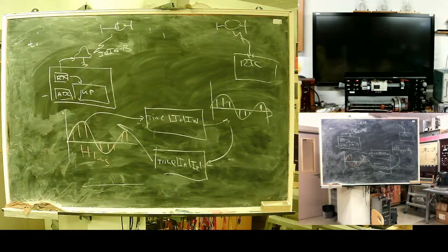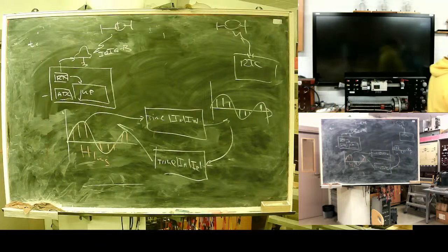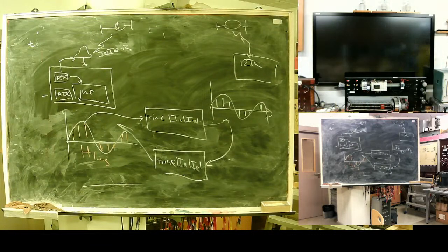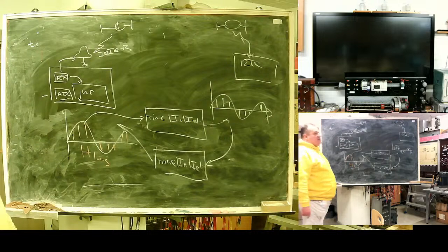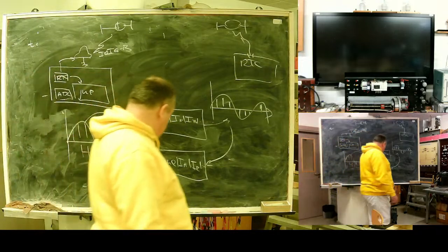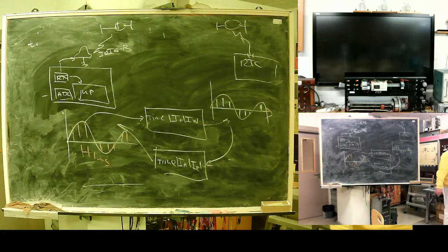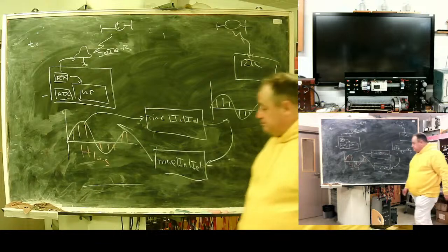Or I saw designs where, to prevent unauthorized access, the fiber optic cable is attached to the lower phase, to keep it under voltage. In such a case, the fall of a line tower means interruption of the data channel. Bad news.